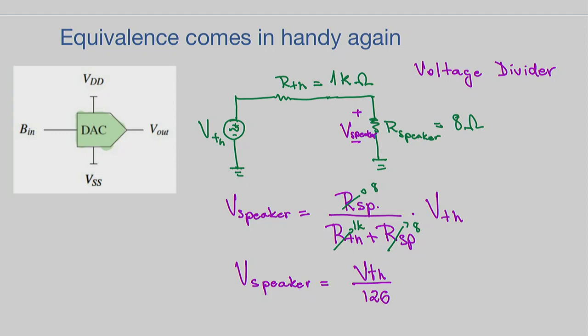Okay. So it means that when we connected the DAC to the speaker, there was some sort of loading effect. Yeah, loading effect. And because of that loading effect, the way we connected things was not right. We did not achieve what we want. So our next step will be to isolate those two components so that we get rid of that loading effect.